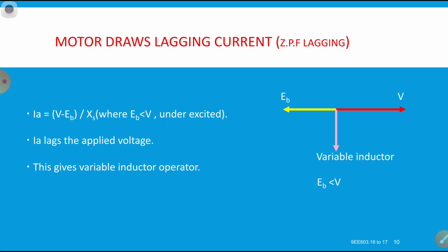Even then, by changing to the maximum tappings in our power transformer in our substation, we are unable to bring the end voltage to the normal value. At that condition, we are going to switch on the capacitor banks in our substations. By using the OLTC, we have generated reactive power. Even then, further we require the capacitor banks to be switched on. Then the terminal voltage is increased to the normal value when the load on our power system is more and more.